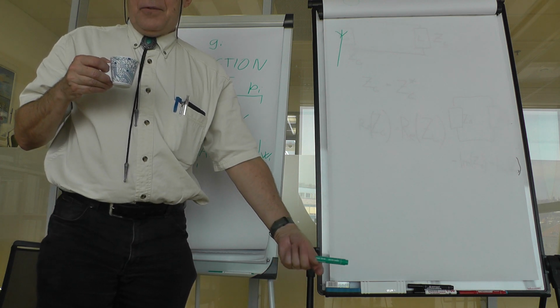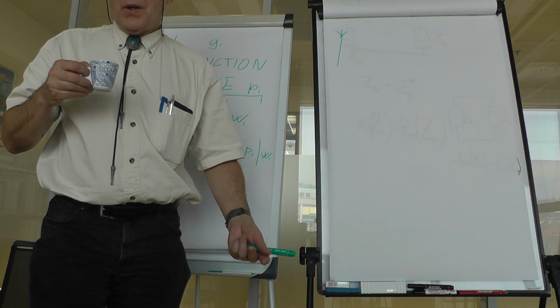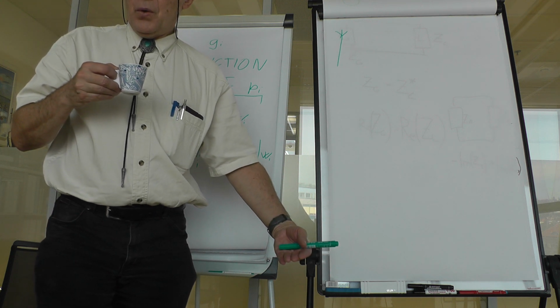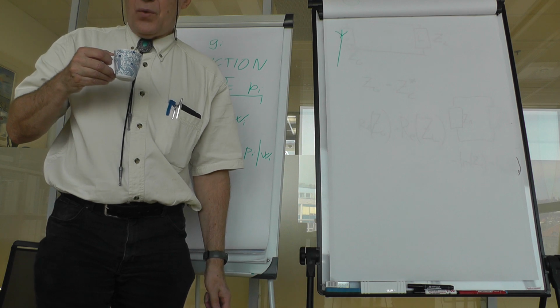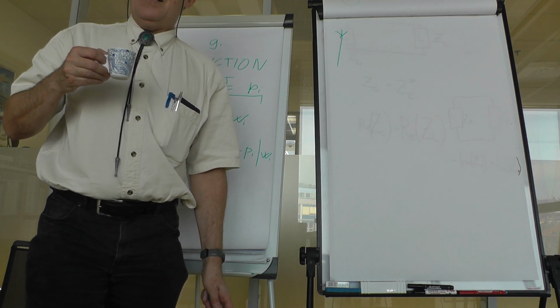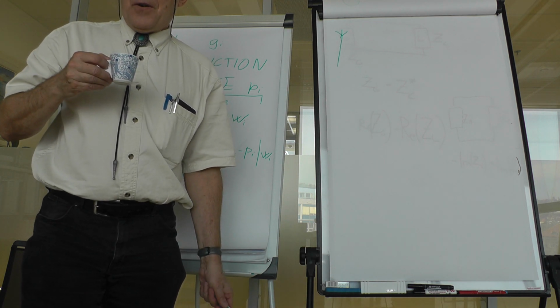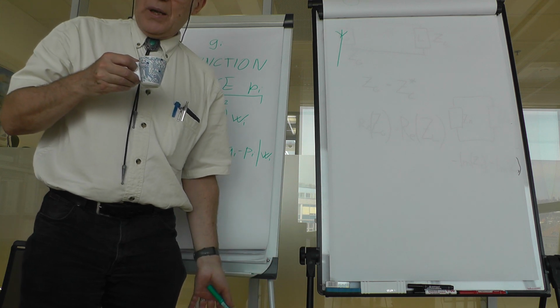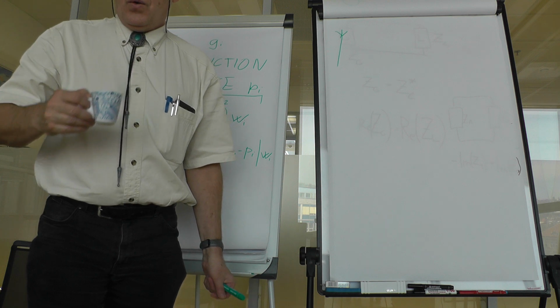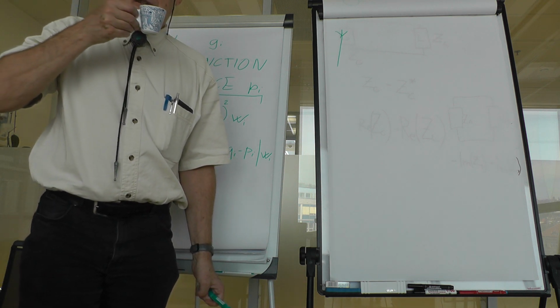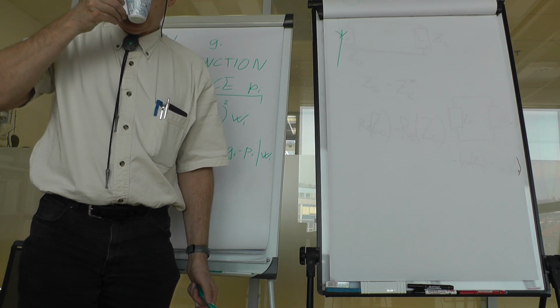Although the frequency is different, 20 watts in the neighborhood creates a strong field that could make it through your input circuits into your receiver and then cause intermodulation, and that's the end of the game. So anyway, you would need to beat that signal somehow.